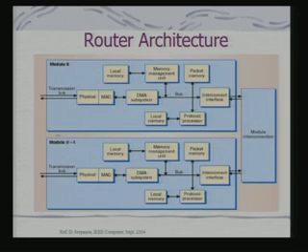So, the router looks something like this. What we have shown here is a router consisting of multiple modules, not just a single module. These two blocks take care of your physical layer requirements as well as the MAC protocol, which we had already discussed, because the router comes at the network layer level. You have your local memory, and this is a DMA subsystem.